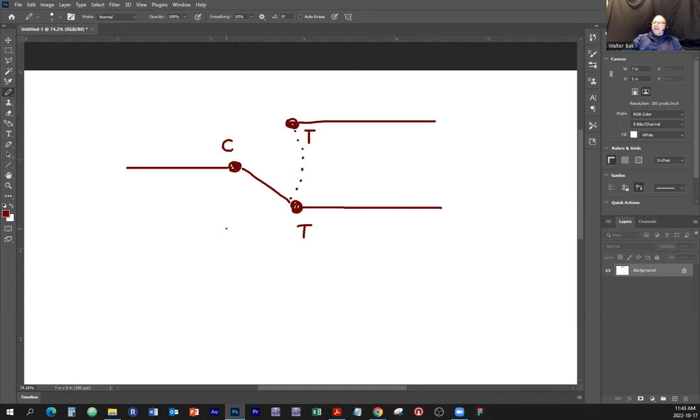Now, if you had that switch in your hand and those terminals were not labeled, and you know it's a three-way switch, how would you test with the continuity meter? Because, well, before you put it in circuit, so it has to be out of the circuit, completely removed, and then you can put a continuity tester onto it. So you would just switch the multimeter into the continuity tester, right? Right. How would you, if they were not labeled, how would you find out which is which?